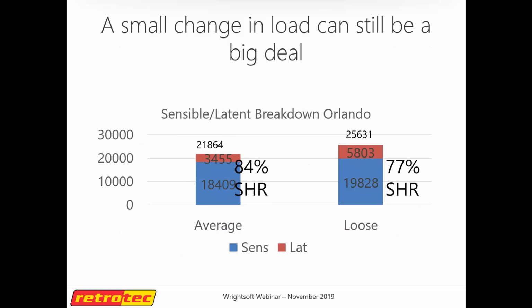And heck, it's not a term some of my HVAC professionals throw around so much, although maybe it should be. Sensible heat ratio is the percentage of, depending on how you look at it, the load in this case, or maybe the capacity of the unit, but we'll focus on the load right now, of the system's job it is to do sensible, right? And so in an average home, I might have an 84% sensible type of job, right?